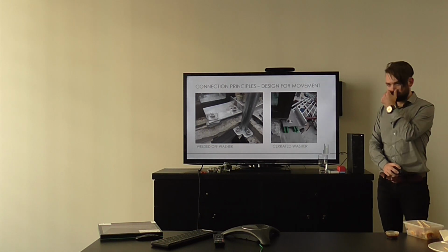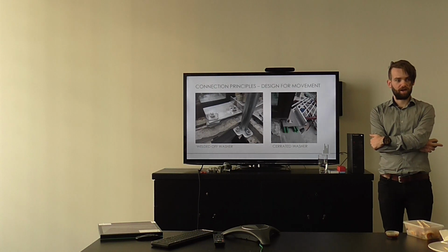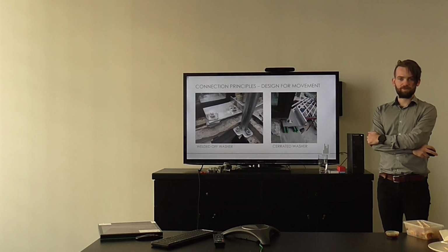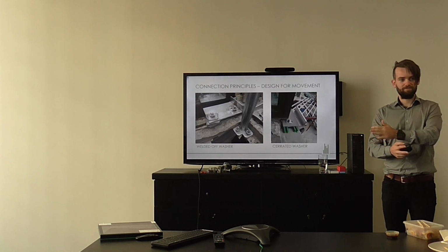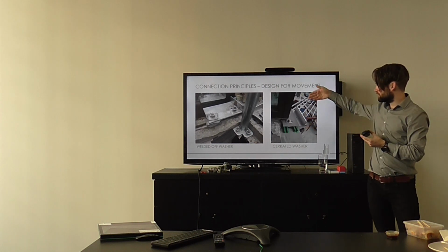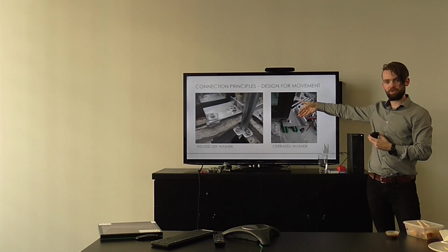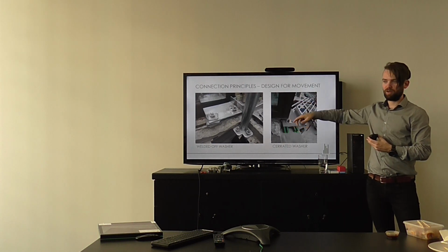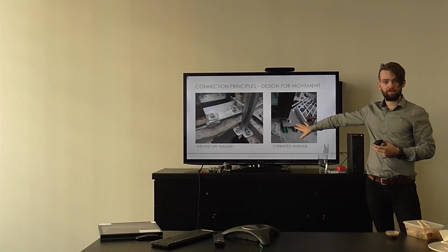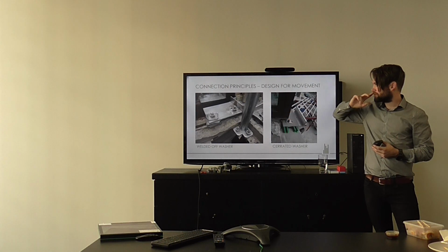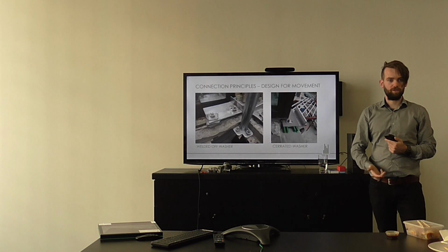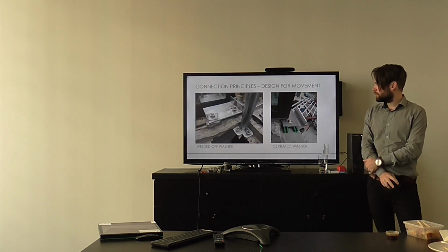Probably some of the best things we can do to deal with tolerance are slotted holes. But we need to be careful with our slotted holes because typically they need to be slotted in the direction that we want them to eventually resist. So in particular in a curtain wall bracket, in this sense here, if you can imagine your wall is here and it's pushing on your bracket, you don't really want it to move in that hole. So some of the tools we can use here are things like serrated washers on serrated aluminium brackets, or slotted holes in steel brackets, but in that case they need to be locked off. So they involve side welding or side screwing. So these are all techniques we can use.